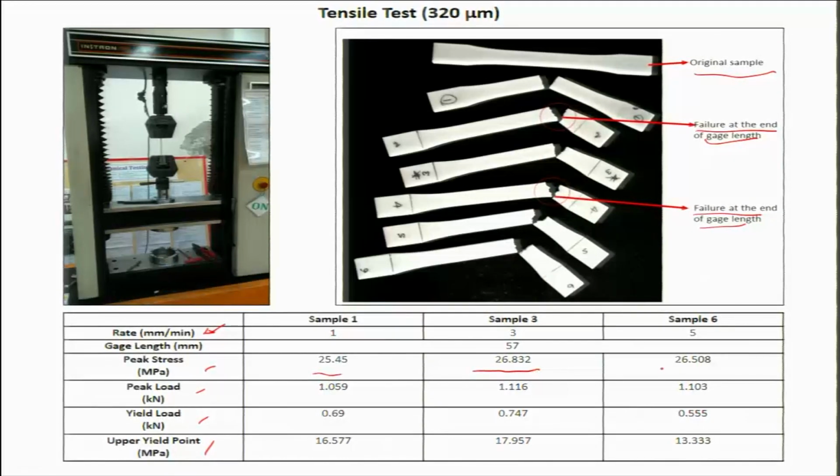printed in a certain direction, okay. And as the direction of printing may change, it may result in the material properties also varying quite a bit based on the direction of printing. So in a way, what can be found out through all these studies and tests is that the mechanical strength, mechanical stability of some of the 3-dimensional parts are highly anisotropic in nature and depend on how the samples are being realized through what direction of printing.